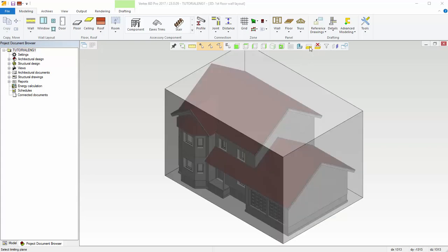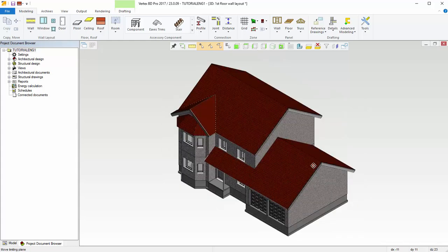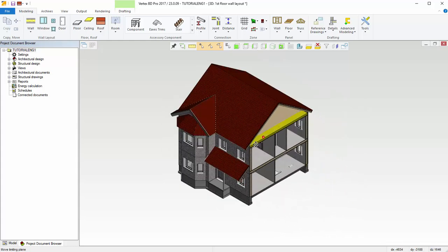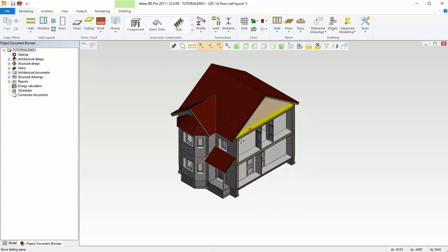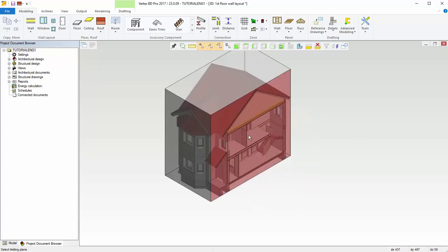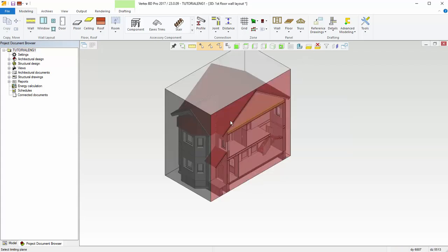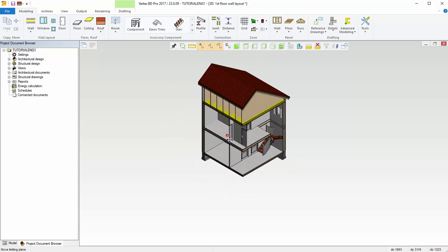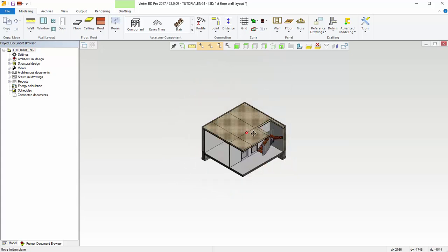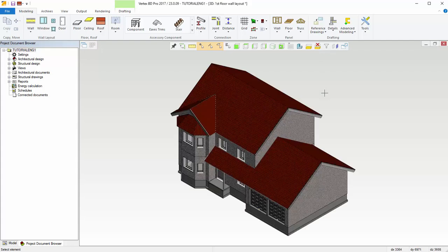The Set 3D Limits function will create a cube around your model, where you can select one of the faces of the cube and then move that face in and out of the model in order to limit the model. Left-click when you have a location and hit Confirm to accept that location. Confirm is pressing down on the mouse wheel or pressing V on the keyboard. You can run the function again to modify the selection and select another plane to limit the model in another direction. To remove the limits, you can select the Delete 3D Limits function.